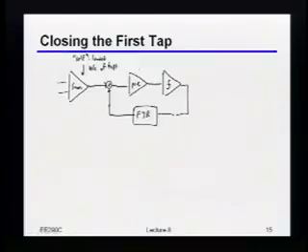Now, if I look inside of the preamp, let's say I do it the way that we talked a lot about in 240, first of all, I try to make that thing have a pretty high bandwidth, which means that I have to spend some power because I'm worried about kickback, right? So I want a low impedance there. But at the same time, this is also a convenient place for me to do offset cancellation. That means that the preamp is going to be loaded by those offset canceling devices. So again, it's going to tend to be quite fast, but still has some loading that it has to deal with in terms of power and speed.